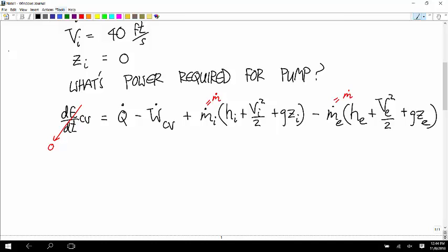And we're given a volumetric flow rate. We're given a temperature. So let's use, the temperature is, what did I say? 64 degrees Fahrenheit. So let's use the saturation table to look up the specific volume of liquid water at 64 degrees Fahrenheit. Okay, and we'll use that for our density, so we can go from gallons to an accurate value for mass.